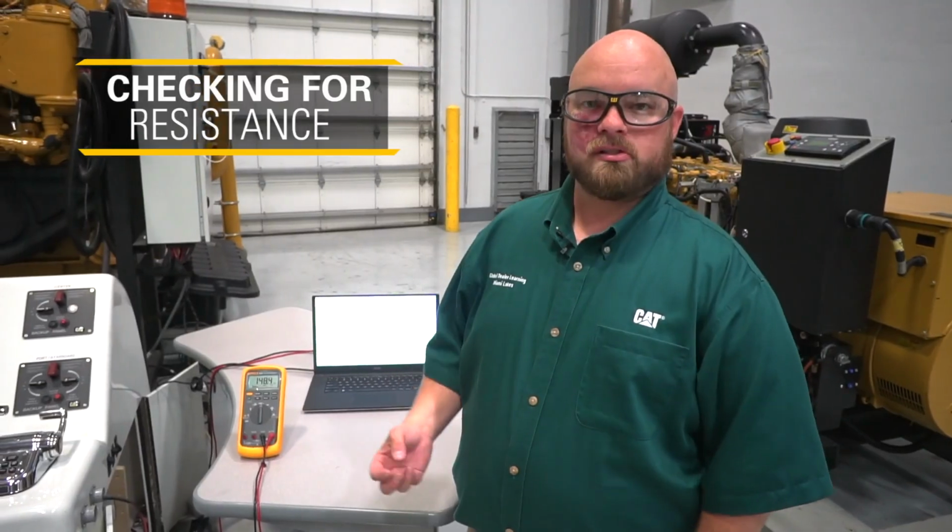Now, these are all parallel circuits, so when we go to measure for resistance, 2 120 ohm resistors wired in parallel, the resistance that we should see with the power off to the system is going to be around 60 ohms. When we're troubleshooting the physical layer on CAN networks, that's one of the things that we're going to look for, is measuring between the CAN plus and minus and see that we see 60 ohms with the power off to the network.